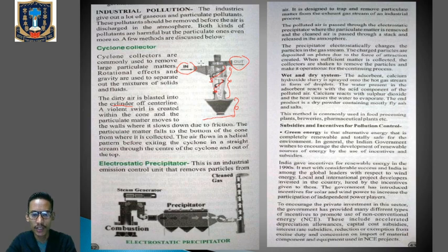That means over here. So over here in this cone, the particulate matter will be collected. So what you think is that through the inlet, the air with the particulate matter will enter inside the cylinder of the cyclone collector, and high velocity air will keep on moving inside the cylinder. A high velocity vortex is created. Okay, that means the air with high velocity will move inside the cylinder, and simultaneously